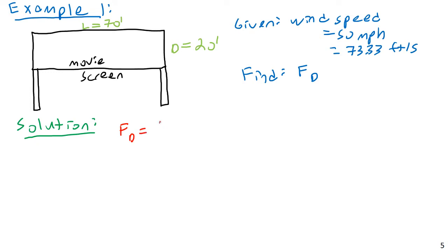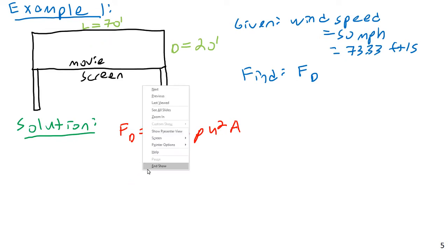So the drag force here is going to be equal to 1/2 times CD times rho times u squared times A. In this case, the characteristic area, since the wind is going into the screen, is the face it's hitting. Obviously the wind could come from any direction, but if this is a very thin screen, the wind coming from the left would be very minimal, and it wouldn't catch most of the area. If the wind was fixed coming from the left, then the drag would actually dominate. But in terms of the overall design, what's obviously going to control is the wind going into the page on this drawing here. So let's look at this.